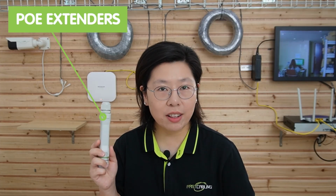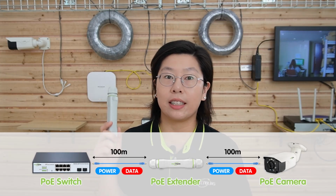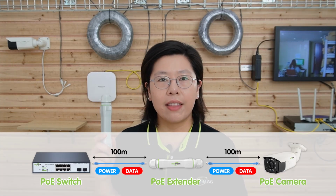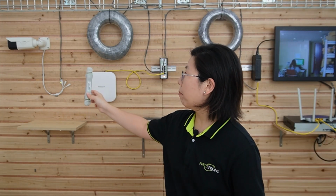If you're aiming for a longer distance in your IP camera network, a PoE extender can be invaluable for extending the range of your Power over Ethernet devices. A PoE extender adds intermediate devices, amplifying and retransmitting the PoE signal, enabling you to reach areas beyond the standard PoE range. You can add them up so you can have a longer distance.